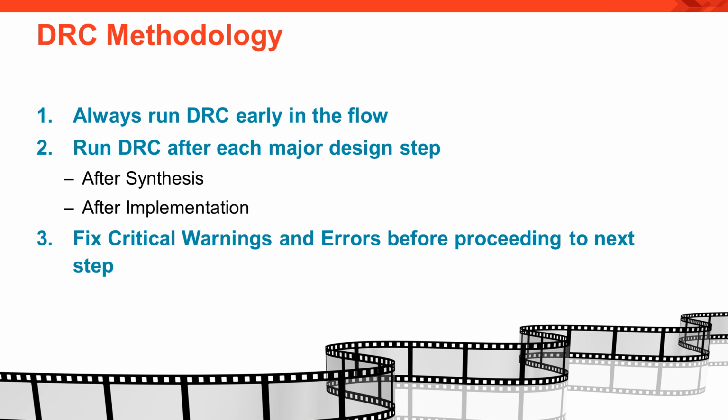With regard to step 2, it is highly recommended that you run DRC after both of these steps. Synthesis is a major step in the design cycle, as this is where your RTL has been mapped over to Xilinx FPGA gates. Before running the place and route step, you should ensure that there are no critical warnings or errors in your DRC report. Implementation place and route is the final stage before generating a bitstream and programming your FPGA. During this stage, many optimization and replications can take place, and thus it is very important to run DRC checks to confirm compliance before generating a bitstream.